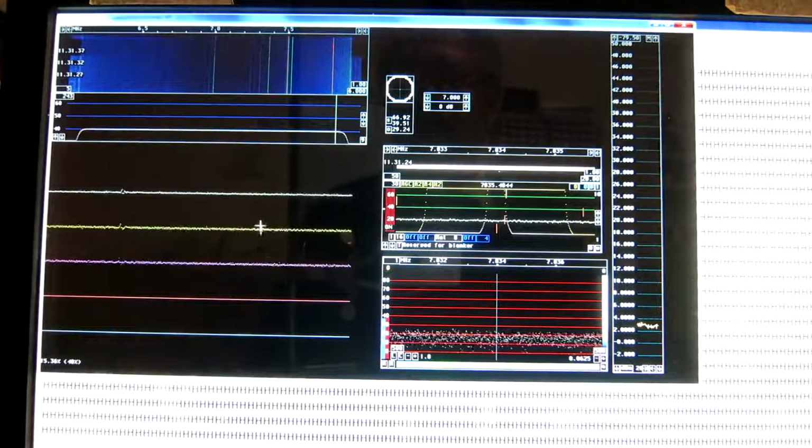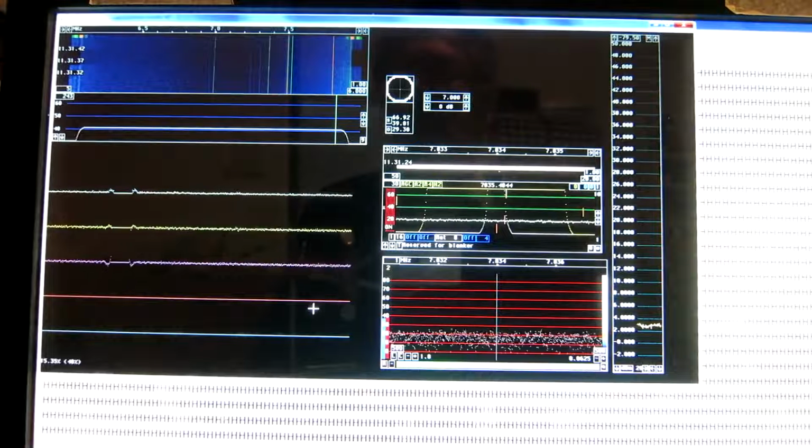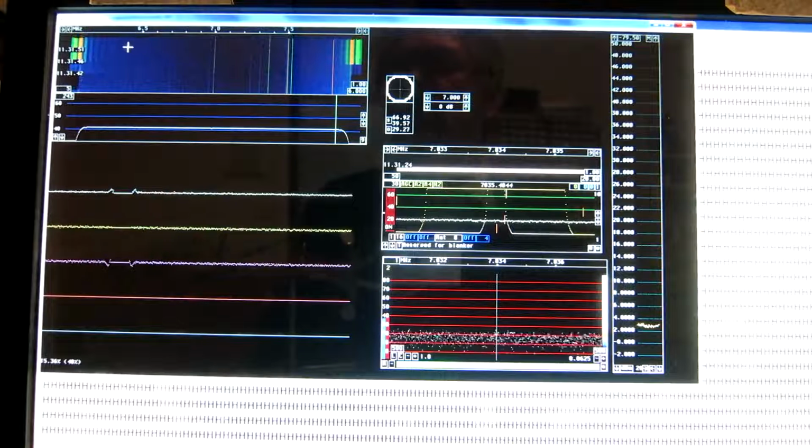Switch on the noise source again. Now running only the dump blanker, you see it cuts a fairly large hole in the signal. There are some artifacts, but most of the spectral region is perfectly okay. The pulse repetition frequency is 720 Hertz because the generator is at 360 and it's a square wave.